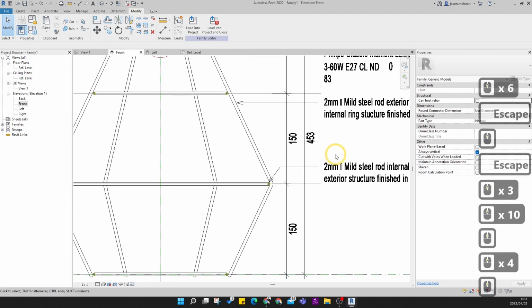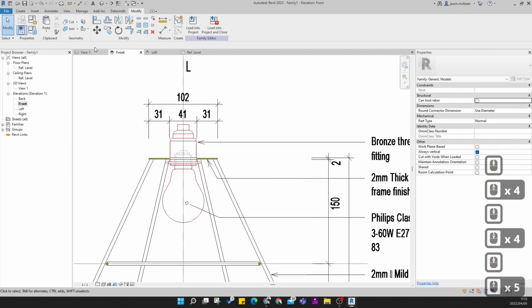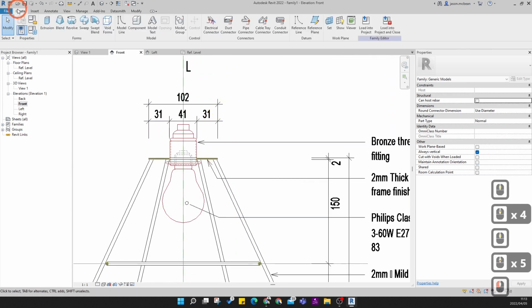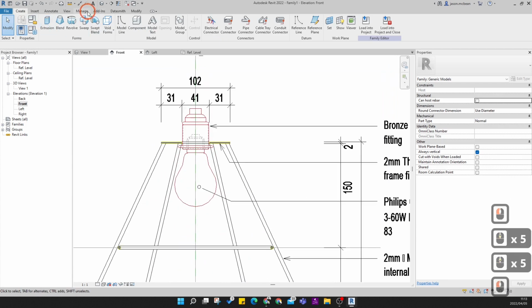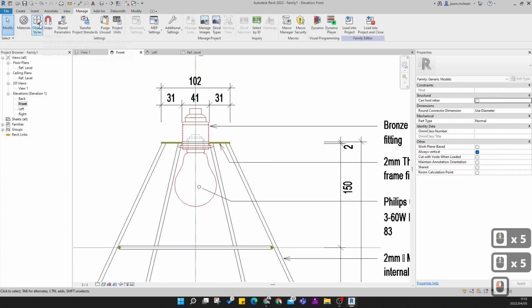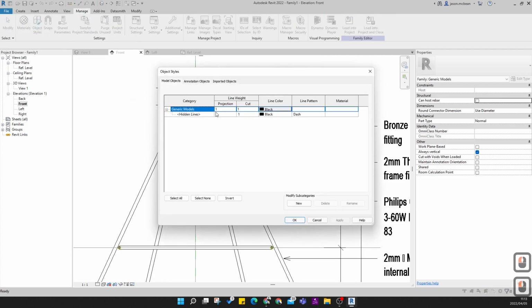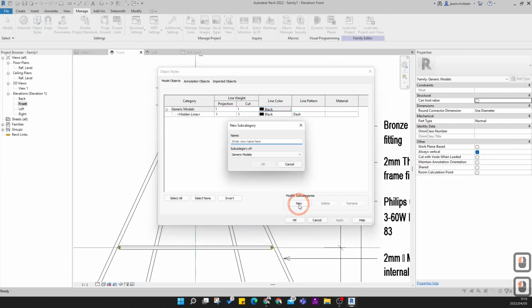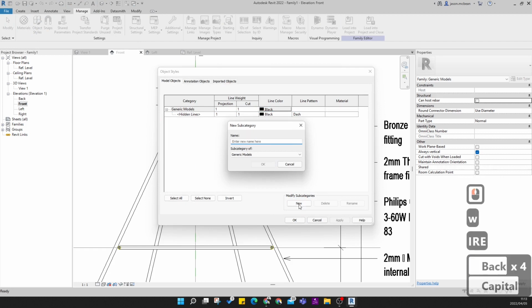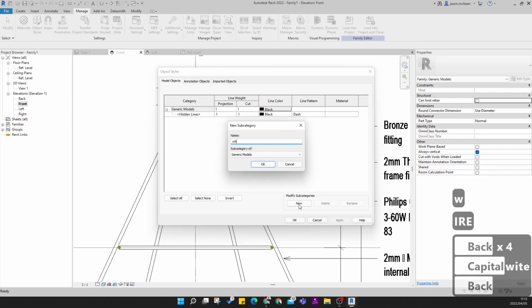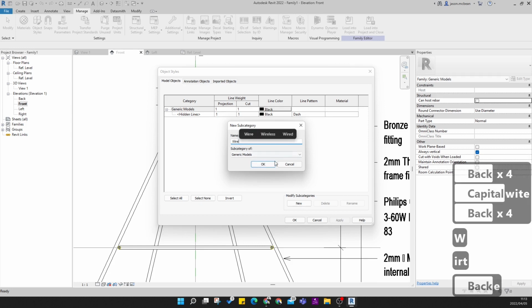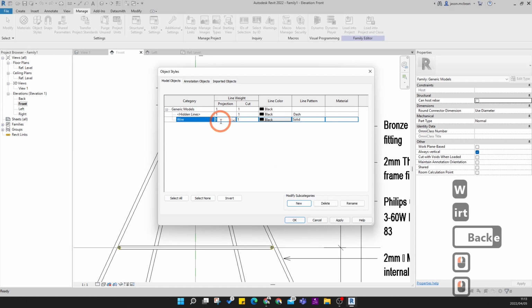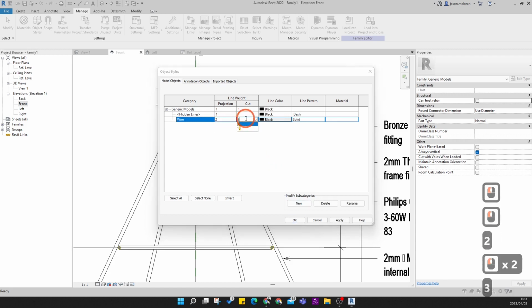All right. So with Revit, which is quite straightforward and easy, we're going to go and create some objects in here. But before I go ahead and do that, I need to go and add some object styles to this. Okay, so meaning it's like layers. So here I'm going to create a wire layer. I'm going to make all of these quite thin. So line weight 2, when we cut, we make it 3.